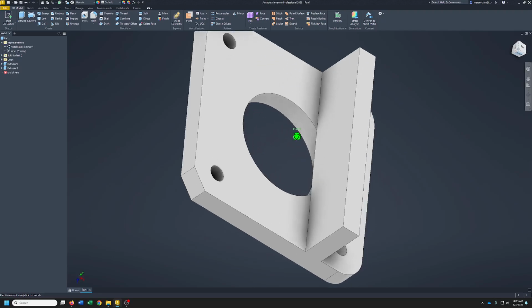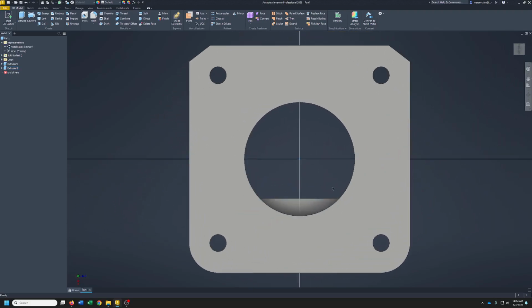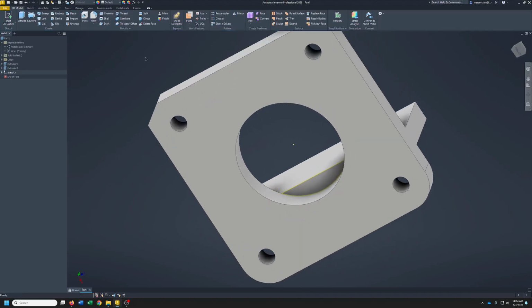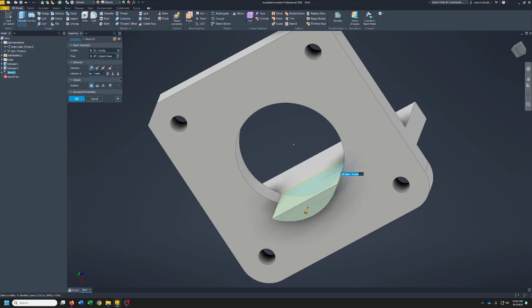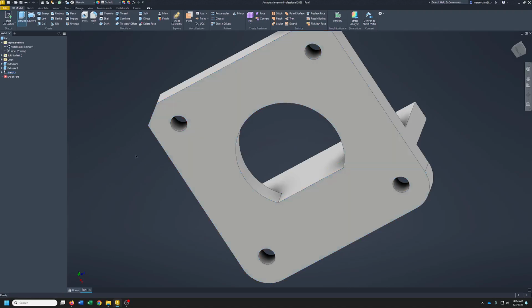Now, can't have that hanging over like that. All right. So I'm going to see all your object options. Okay, I'm going to create a sketch. And I'm just going to project geometry and I'm going to pick that face. There we go. Now, finish. Extrude. Pick 2 and pick this face. And it fills the hole. And there we go.